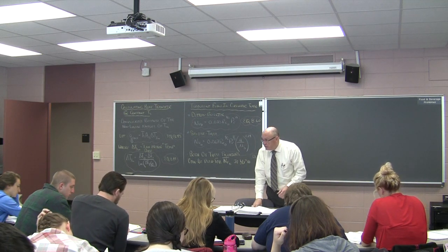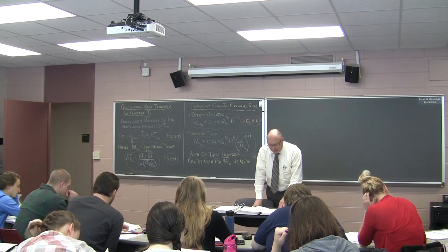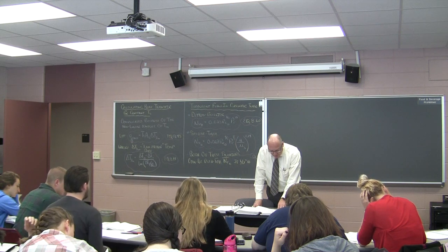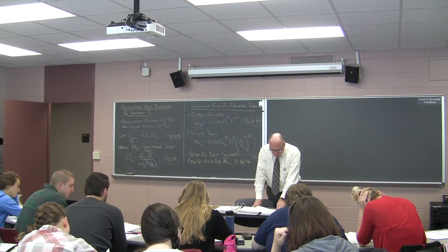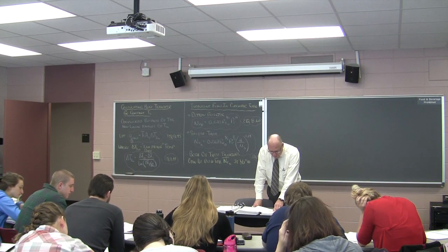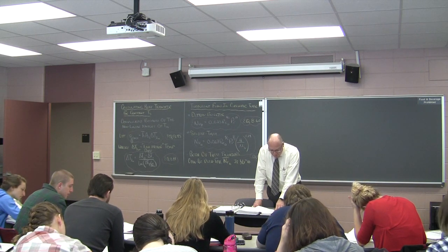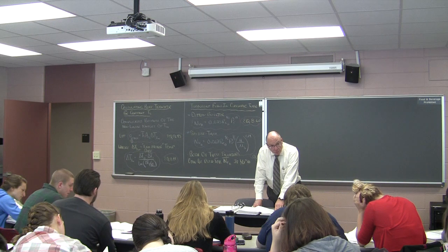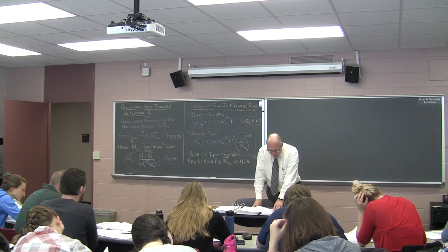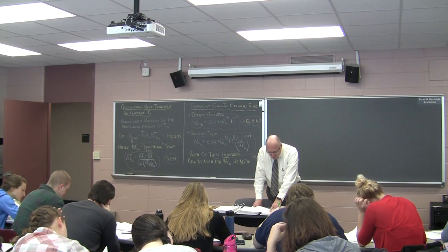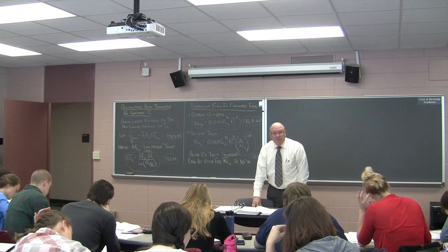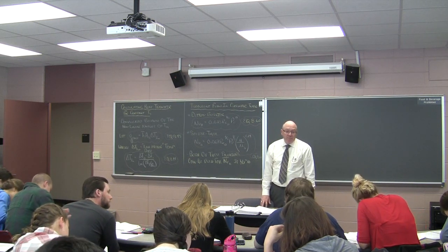Okay? That's why it's given the subscript s. And it says, where all properties are evaluated at Tm except for mu sub s. To a good approximation, the foregoing correlations, that is both Dittus-Boelter and Sieder-Tate, may be applied for both the uniform surface temperature and the constant heat flux conditions. Okay? So you can use them for both.